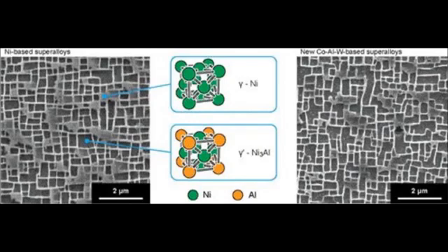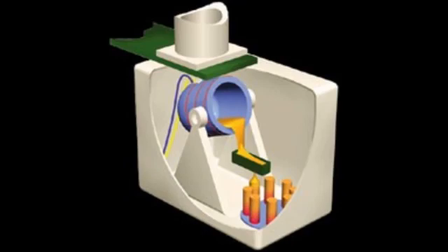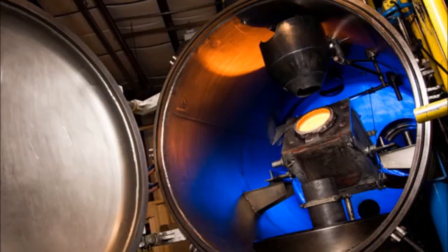The air melting process used to create the superalloy blade included aluminum and titanium elements, which strengthened the material, however, creating low ductility. For a blade to work successfully, it needs to be a combination of strength and ductility. That is when, in 1953, the innovation of vacuum induction melting, or VIM, made the jet engine what it is today. VIM uses magnetic currents to melt metal. The metal is melted with a current, then molded into the blade. VIM boosted alloy capability by 200 degrees Fahrenheit.